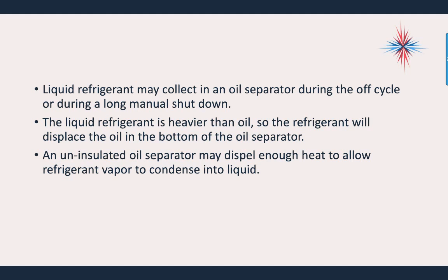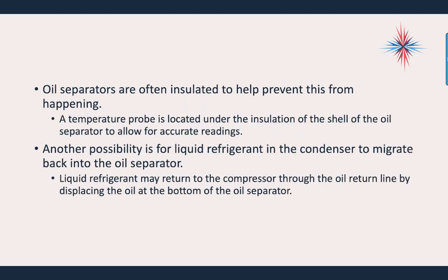If you have a condenser with an oil separator outside, and if the temperatures drop low enough, you can actually trap liquid refrigerant in that oil. Oil separators are often insulated to help prevent this from happening. A temperature probe is located under the insulation of the shell of an oil separator to allow for accurate readings.